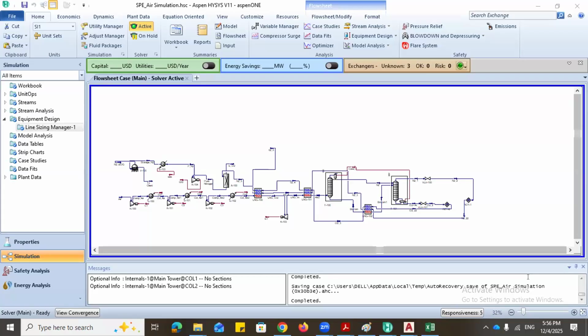They say, I want to ask, what is the typical step for a typical project? What comes first and what follows? Simulation, material and energy balance, PFD, P&ID, line sizing, and equipment sizing. Oh, see, take note. First is the simulation, right?